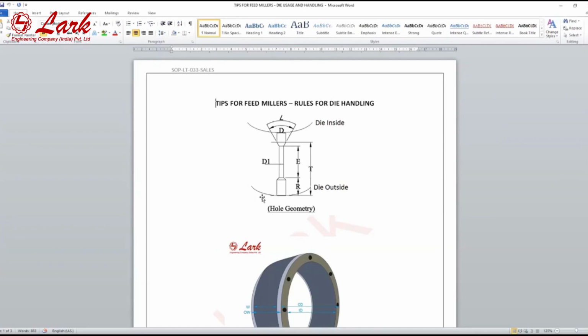If someone says my PDI is not good, I have to increase the PDI, and my formulation is rich in oil content, I need a die with higher L by D, like 1:13 or 1:14. 1:14 means 14 into 3 is 42. The effective area will be 42 mm and the relief will reduce to 8 mm.